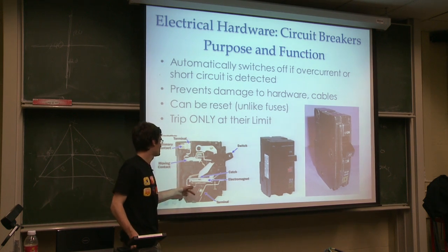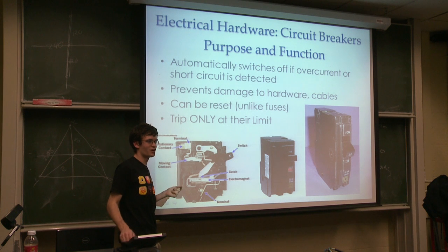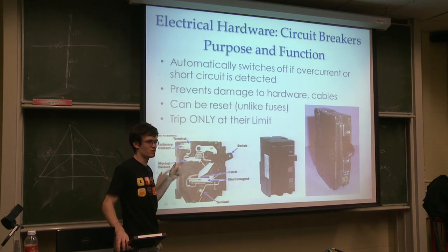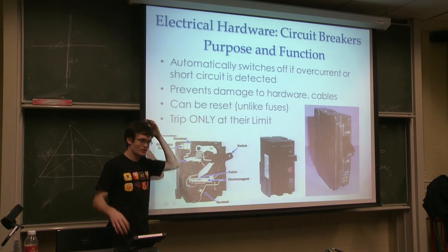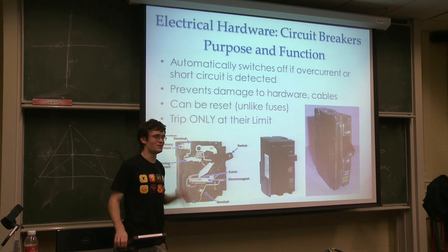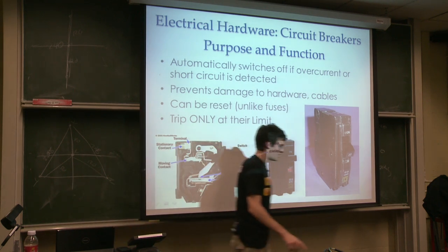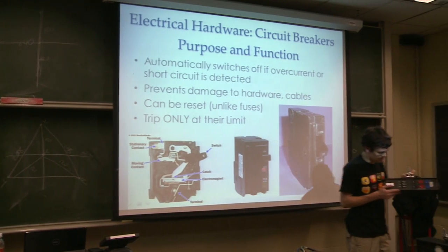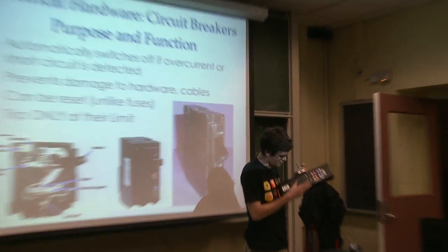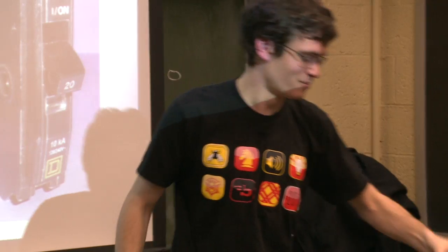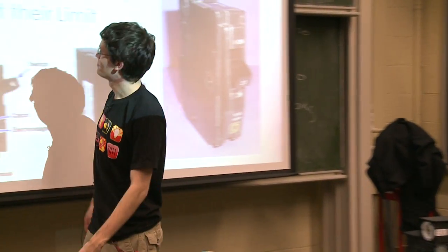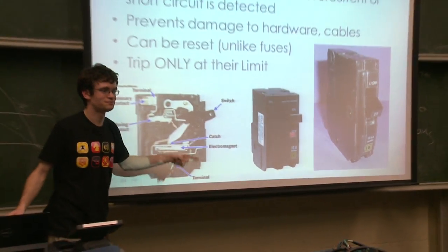They're also made to somewhat high standards because you want to be able to load up a circuit up to its rated value, but you want the circuit breaker to trip when it hits that rated value and not 10 amps over. So they are somewhat well designed to be at a very particular value. So I have a couple boxes that have circuit breakers on them, and you can switch them on and off if you want. I will explain these boxes more later, but if you really insist on playing with the circuit breakers, they're there. The circuit breakers make sense?